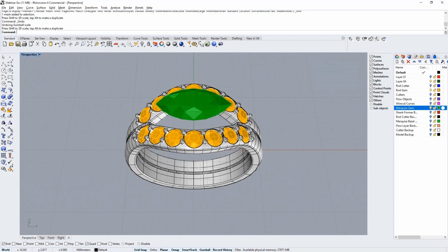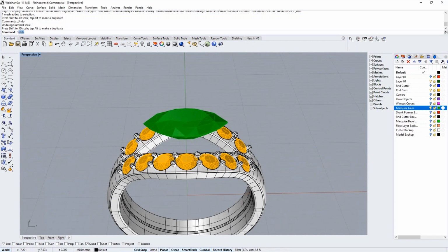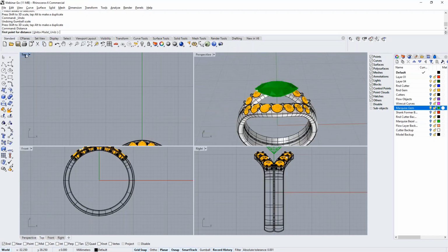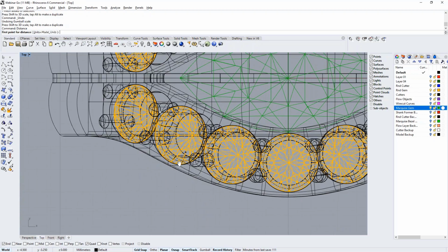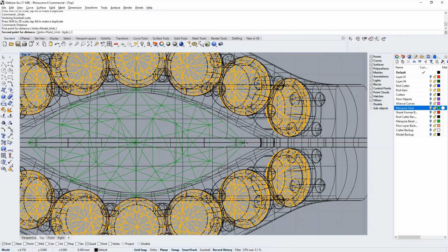So all of the trimming and unioning that you've done is no longer working, and that's when we get the models. And then we open them up and look at the tolerance. It's like, wow, there's no way that you can manufacture to this. So usually we say one step more precise than what you're manufacturing to is all you need. But you want to have enough precision, but you don't want to overdo that, because that's going to cause problems down the road.